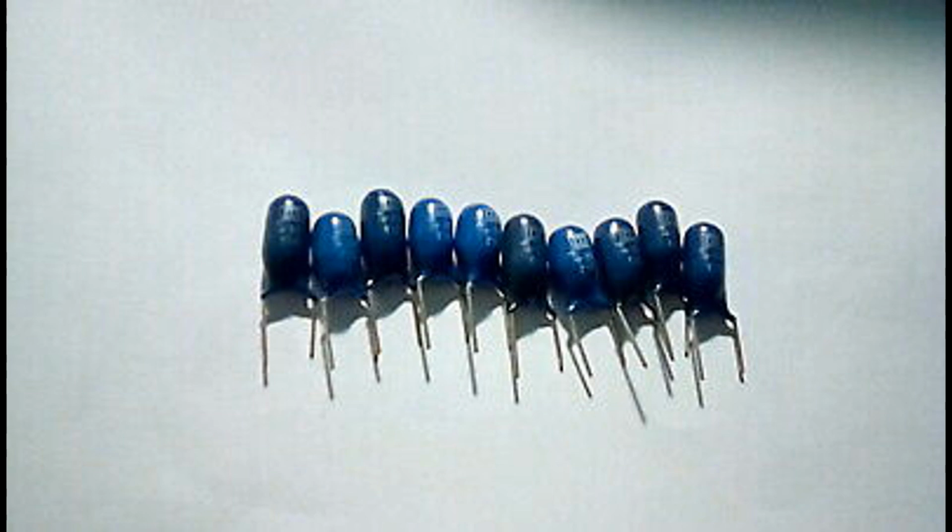3. Cathode. Manganese dioxide, MnO2. The cathode is typically made from manganese dioxide, a conductive material that is applied to the surface of the dielectric. This is done through a chemical deposition process where manganese salts are converted into manganese dioxide, forming a layer on top of the dielectric.